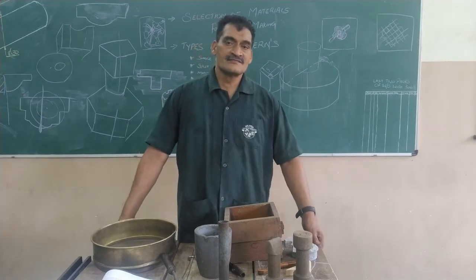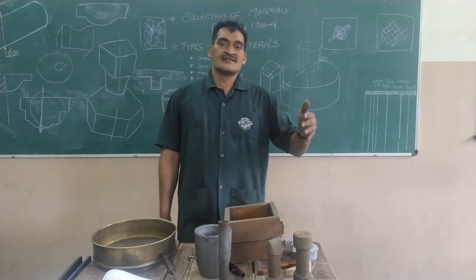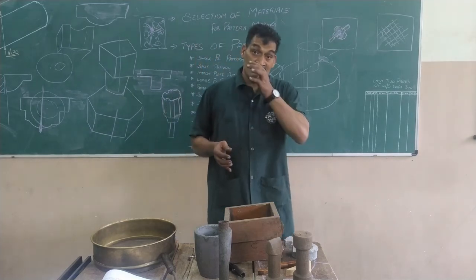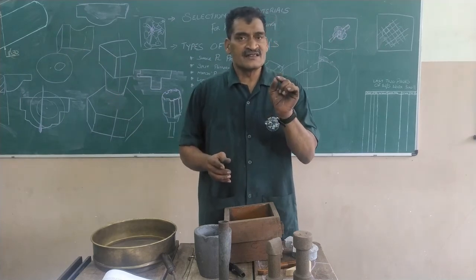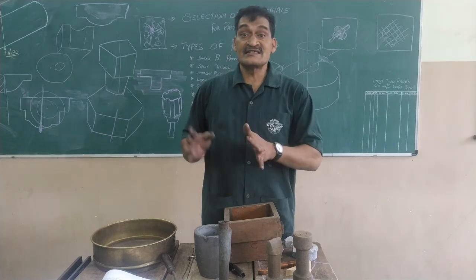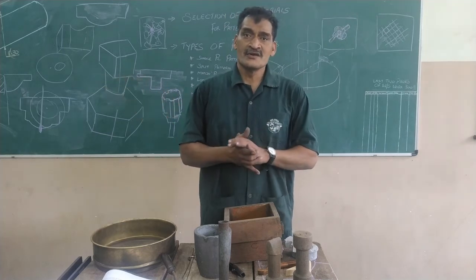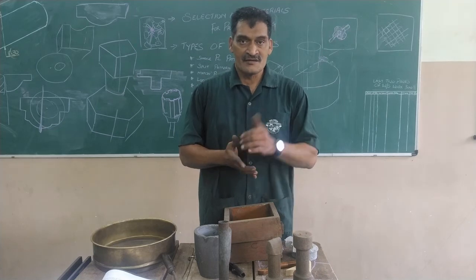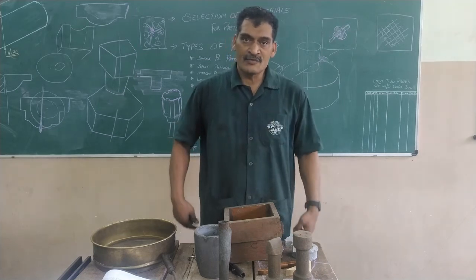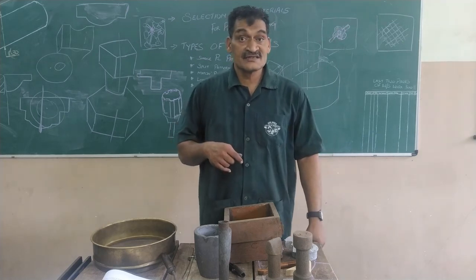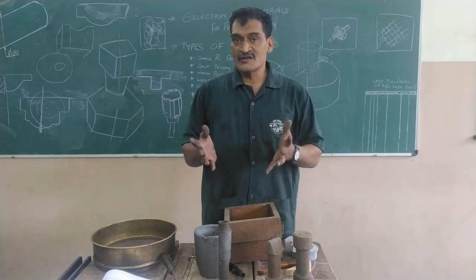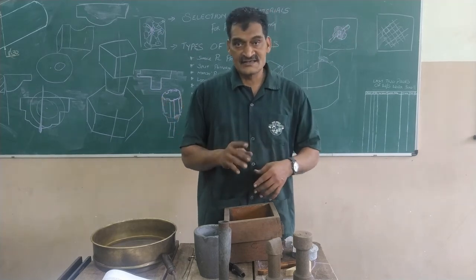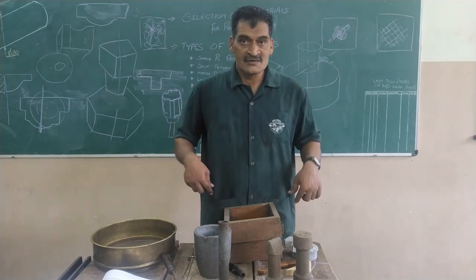As far as safety is concerned, first we require PPE. Now, the PPE that we require in the foundry shop is slightly different from the other shops. It is somewhat the same as that worn in the welding shop. One will be your boiler suit, lab coat, then we'll have closed shoes. Then, since we are dealing with hot work, we require leather gloves. We will have the apron.